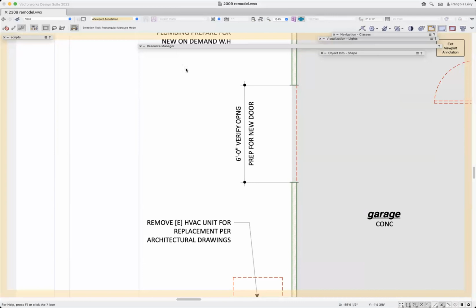And the flooring issue is an interesting one, and depending again on the level of precision that you want your drawings to communicate, you might actually take that up in your stories, right? So you might have a finished floor that's say 5/8 or 1.5 inches or whatever is appropriate above the foundation, the top of foundation or top of subfloor.